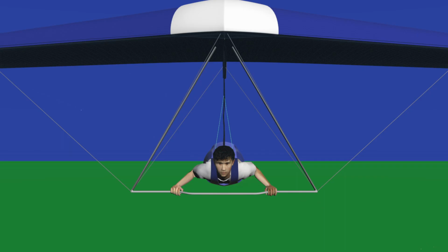Let me bring back the hang glider for now. A pilot steers the hang glider to the left or right by shifting his or her weight to the left or right. Here is a slowed down animation that shows how it works. The glider is at this moment flying in a straight line in the direction of the camera. The pilot is attached to the glider at this point, and the center of mass of both pilot and glider is somewhere about here.